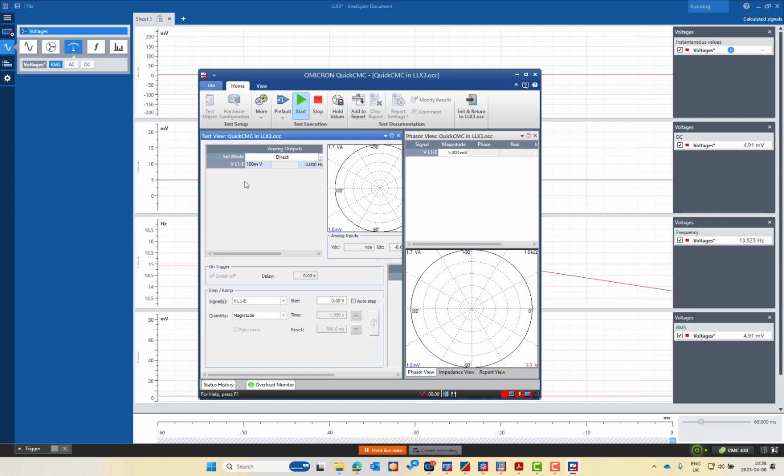We can increase to 10 millivolt. So it's 9.94 millivolt. And if you are increasing the value, I think you will find more and better accuracy. Like if we injected 20 millivolt, it will be 19.94 millivolt. So we can inject more than that, like 50 millivolt. Yeah, it's 49.94 millivolt, which means 0.06 millivolt error.